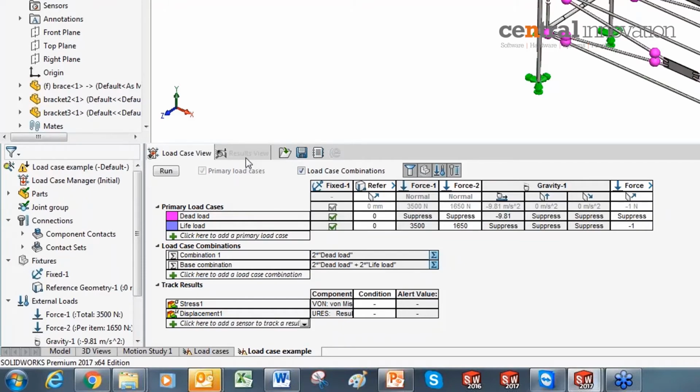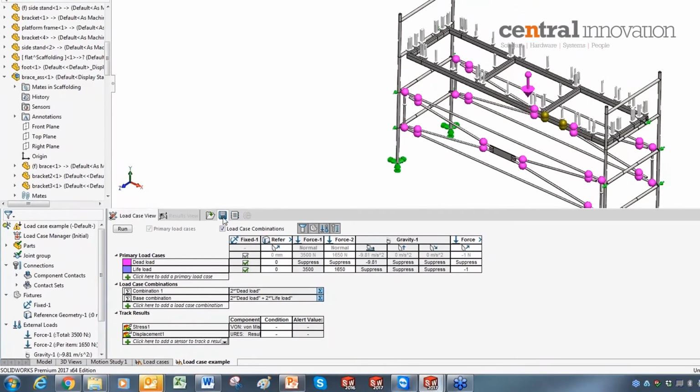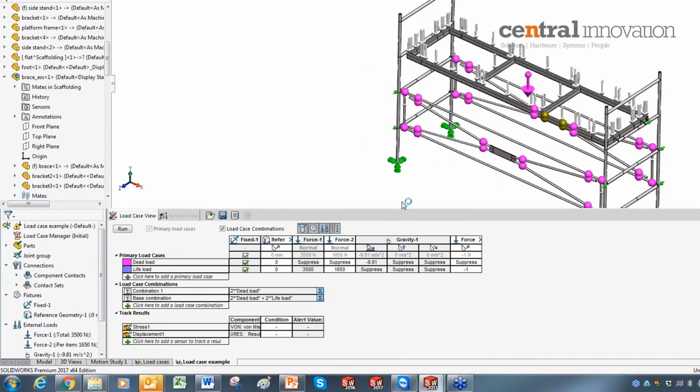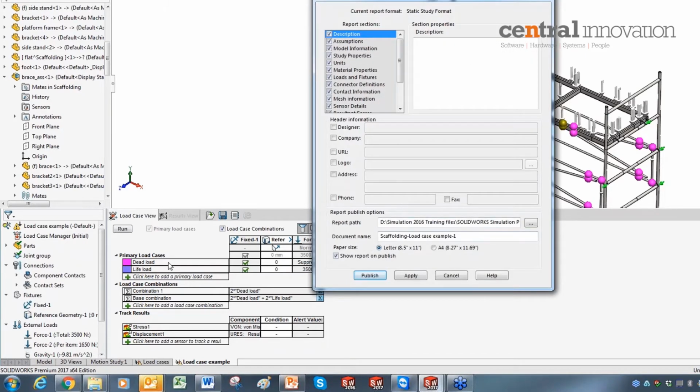And before you run, let's say I don't want to run a selected combination. You have this option in here. You can choose to untick the combination which you don't want to solve. I don't want to solve this combination one. You can untick this and click OK. Means it will run only the 3 selected combinations.